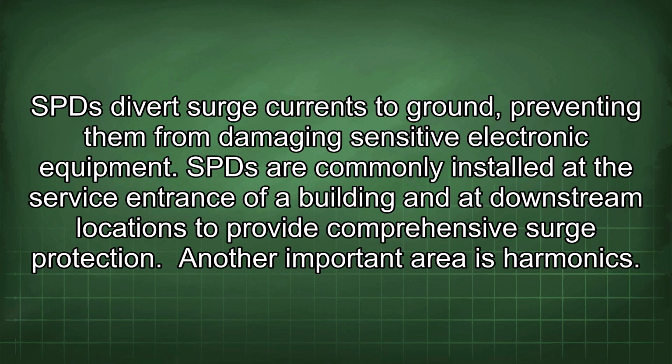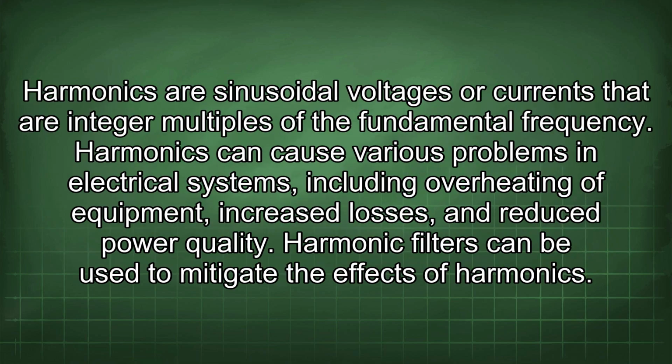Another important area is harmonics. Harmonics are sinusoidal voltages or currents that are integer multiples of the fundamental frequency. Harmonics can cause various problems in electrical systems, including overheating of equipment, increased losses, and reduced power quality. Harmonic filters can be used to mitigate the effects of harmonics.